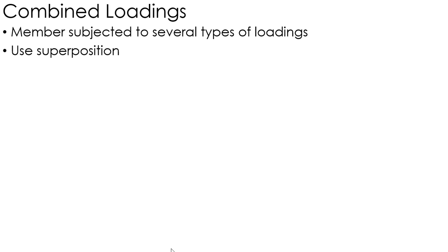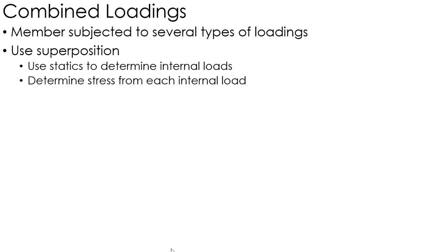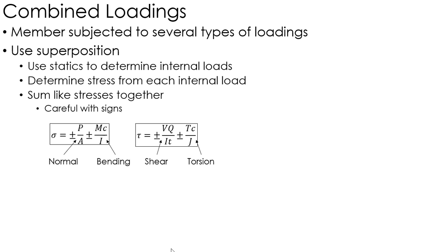Now, this is another one of those things where it's probably just going to be easier for you to go look at the example on how to do it, because we've done all this stuff. It's just applying it in different ways. So what do I mean by applying superposition? Well, you use statics, you figure out your internal loads, any shear, normal, bending moments, torsions, that sort of thing. And then from each of those loads, you figure out what the stress is from each of those loads based on where it's located, what kind of load it is, all that good stuff. And then basically you sum them together, and that's the idea of superposition.